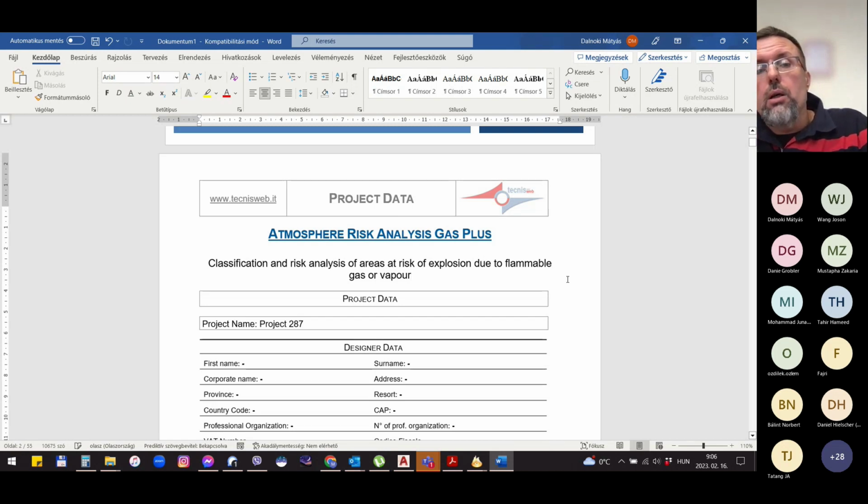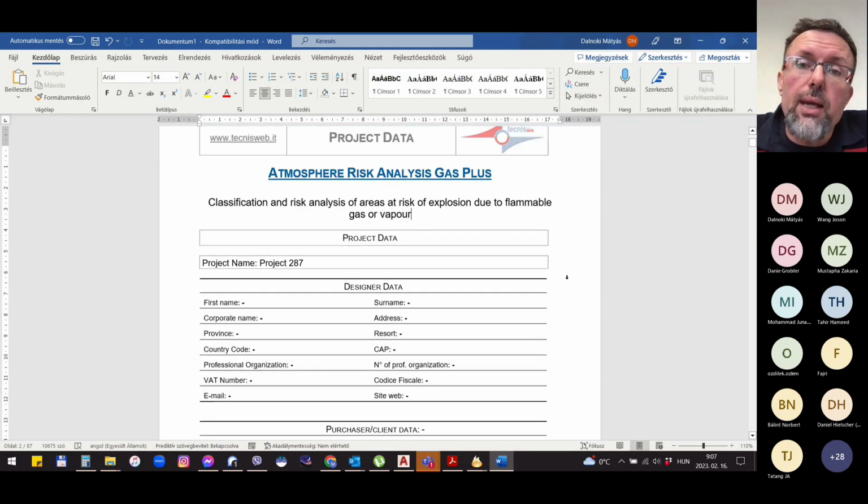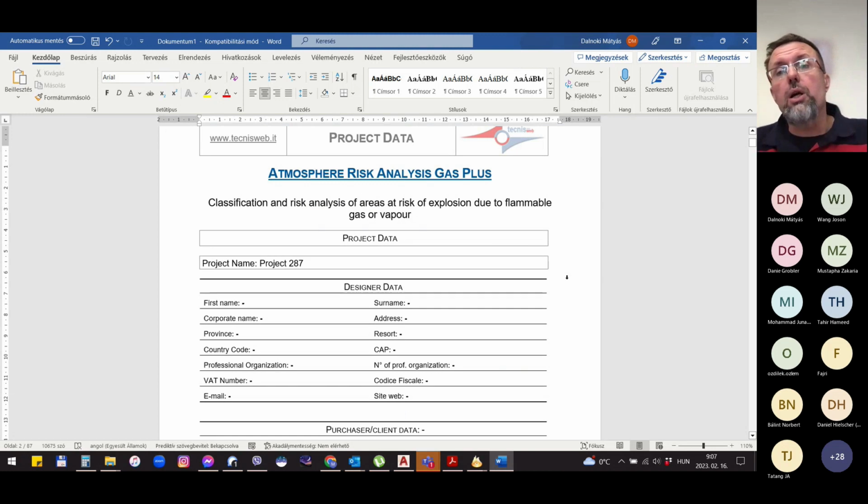This data you can source from the software if you give it there, but you can rewrite it. Okay, and don't forget, the hazardous area classification is a legal document. The legal document has to be signed and revalidated from time to time to confirm that we still comply with it, and has to be followed very strongly, okay? And that, once again, is a legal requirement because all other disciplines are designed based on your risk assessment, and based on the results of your hazardous area classification.